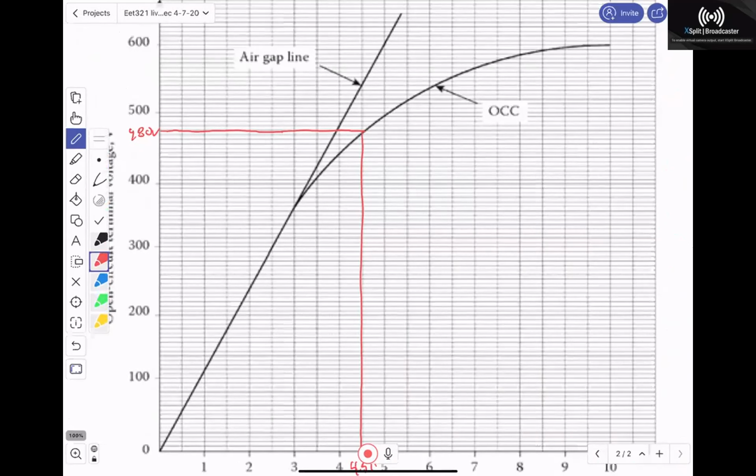So let's say that it's approximately here. Again, this is ballpark because the quality of the figure is not great. Then I draw a straight line as best I can and drop down. So what is that, 5.7 amps or so of field current to deliver 1,000 amps to the load at that 0.85 power factor.